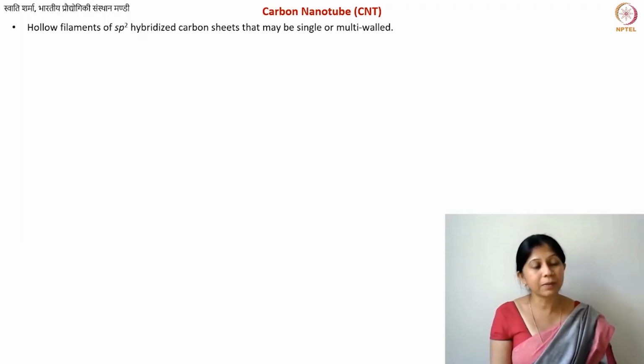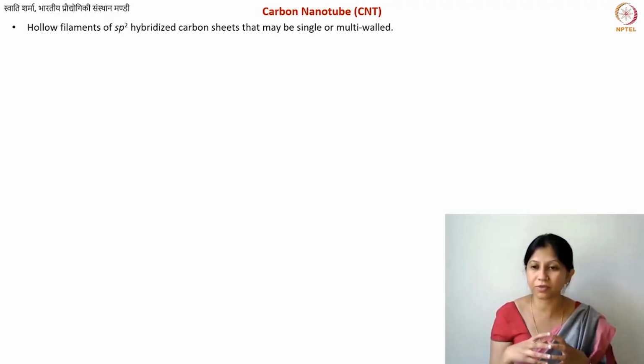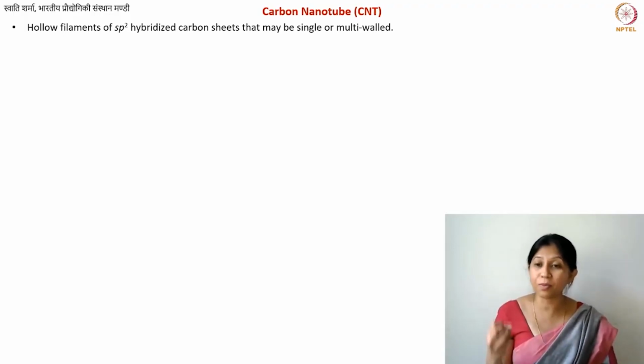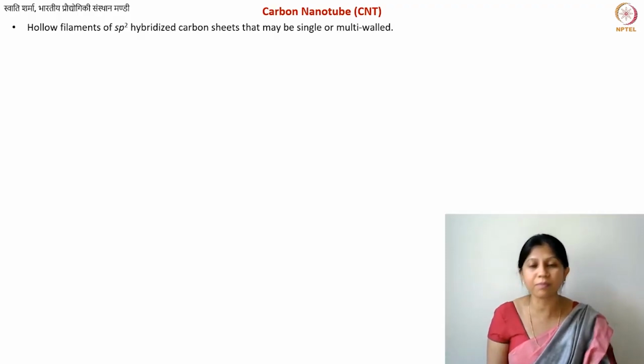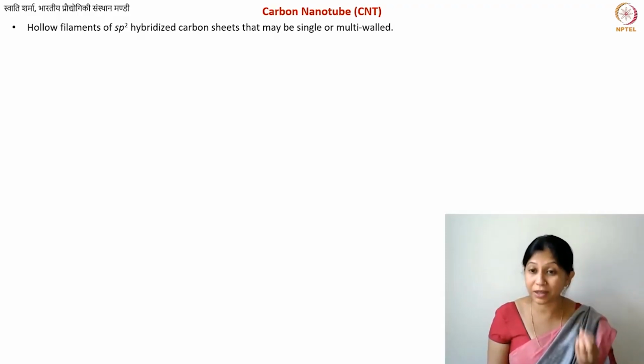Whenever there is vapor of carbon, and there is also some metal nearby, and there are high temperatures, that is when you will have vapors of carbon. When we say vapors of carbon, typically you're cracking a hydrocarbon, or you're performing some very high energy manufacturing processes on graphite, like laser ablation of graphite or any other type of carbon. In that case, you may have these vaporized carbon atoms, and they contain a very high energy. At that time, if you also have a metal catalyst present, then 99% you're going to get some sort of carbon deposits.